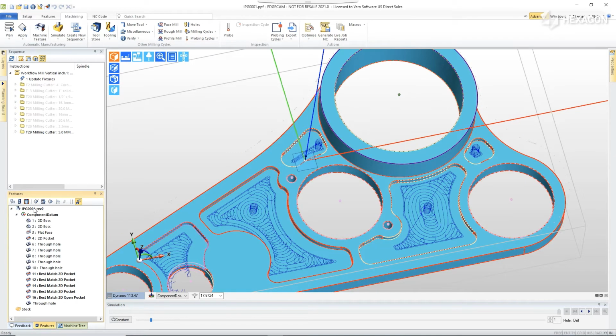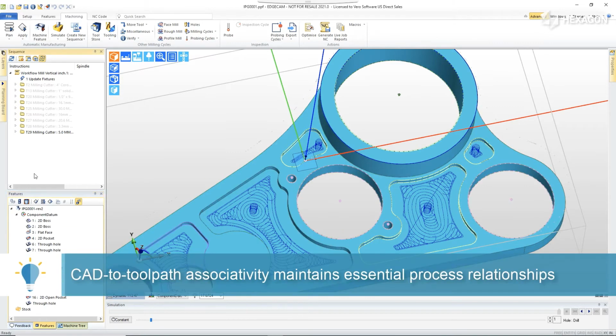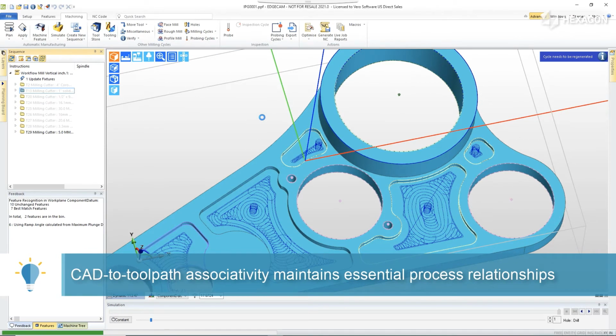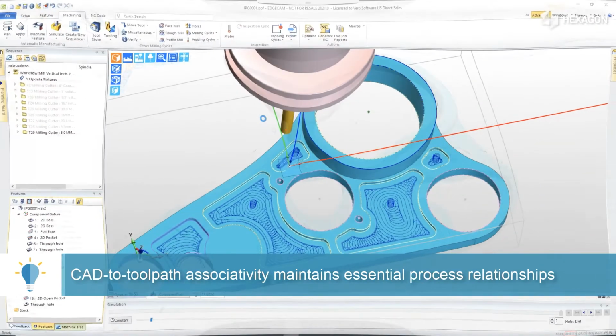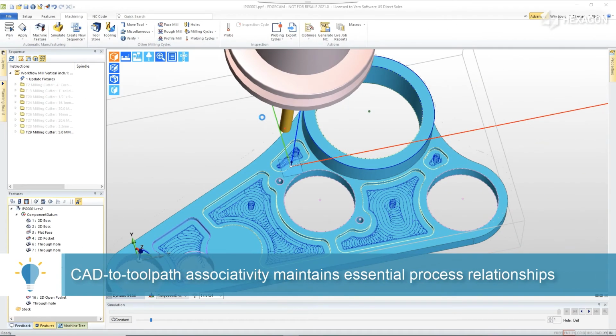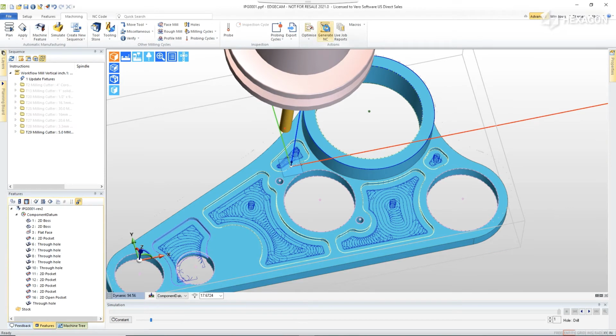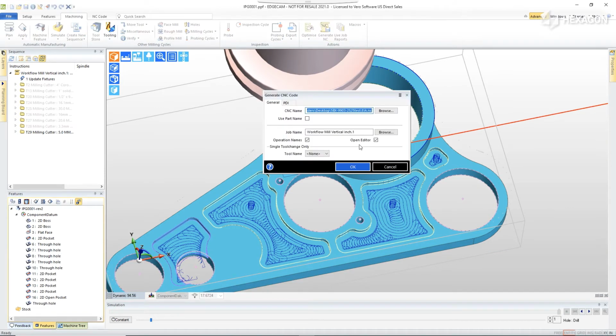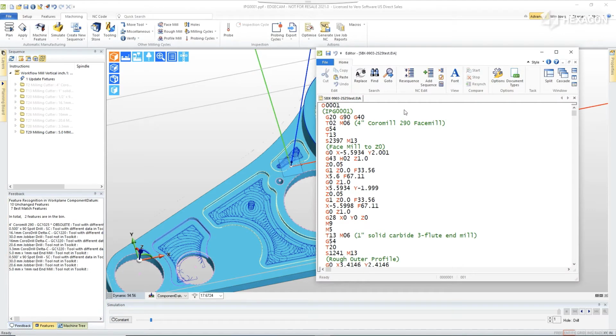Next, we'll go rebuild that machining process, which updates the existing toolpath to the model. The current view has isolated the toolpath in these pockets for visibility, and notice the results when the toolpath is rebuilt. It's now updated the existing toolpath to work with the latest solid. We're ready to now immediately move forward, generate code, and then send that code directly to the CNC machine.